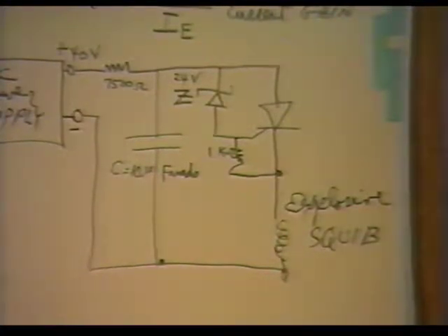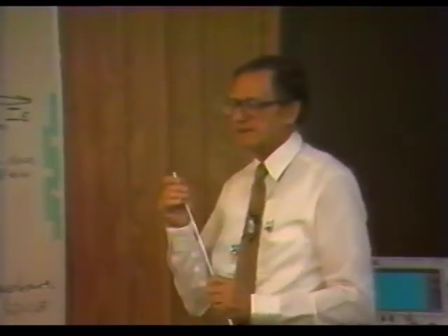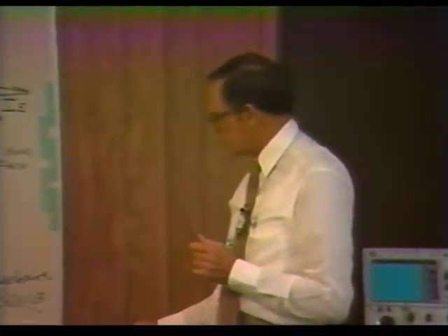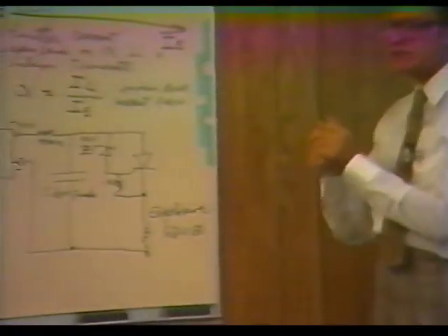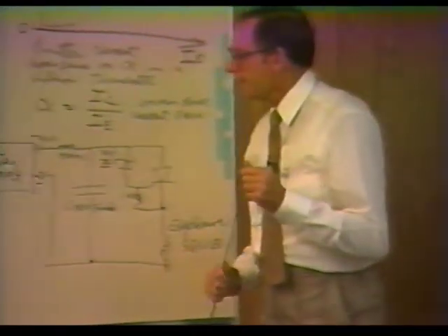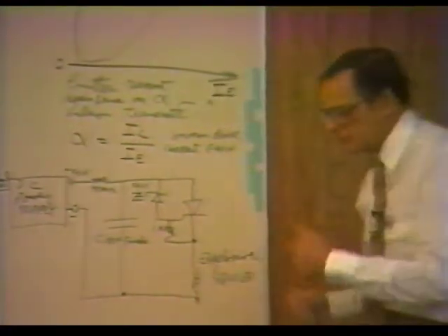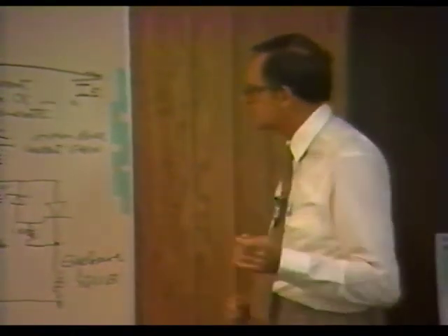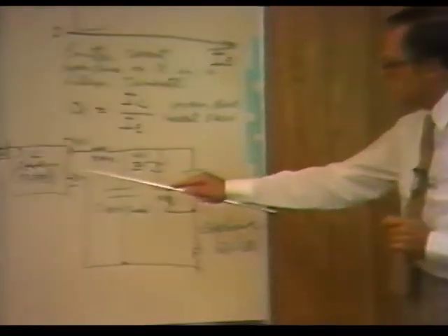And the explosive charge now usually drives a piston, because the gas from the exploding charge exerts a great deal of pressure, and it drives a piston. And this piston, in this case, we fire the explosive charge, and the piston opens the tail fins, and the weapon falls away. Now other things happen inside the weapon, and we do use SCRs at other places, but this is a little hypothetical case. Now here's the way this works.